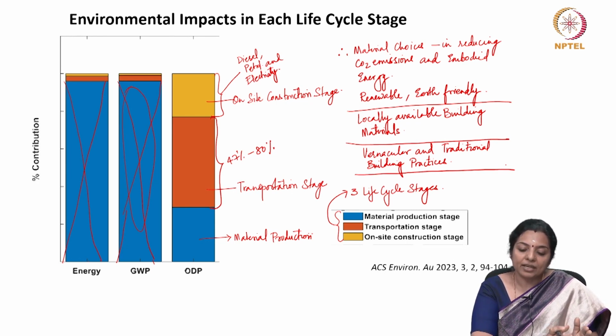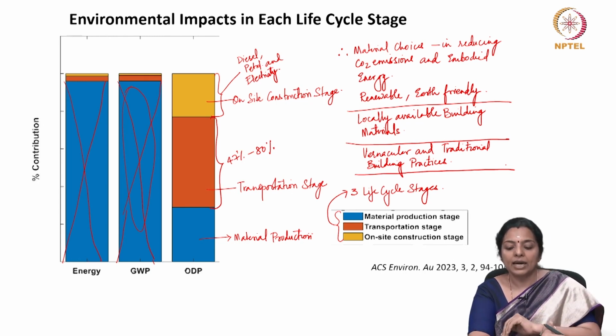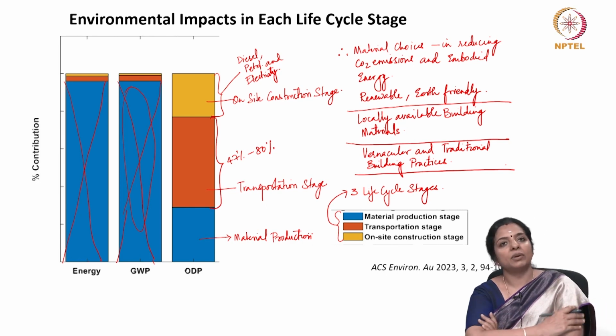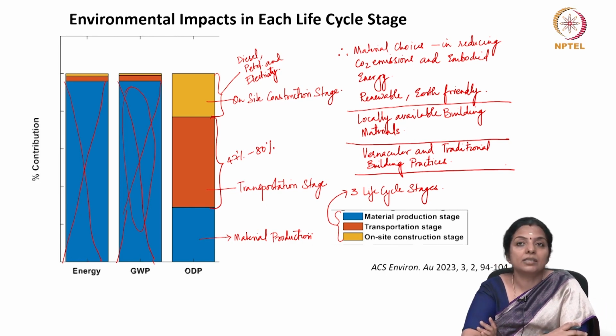Try to source the materials from local places, very close to your building site, and try to use construction technology practices which are not energy intensive. In the previous classes, when we were discussing technologies with renewable materials, you saw the jack arch roof and the filler slab. These do not require very heavy machinery as compared to many other construction techniques.